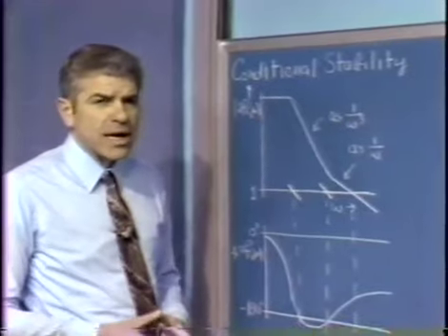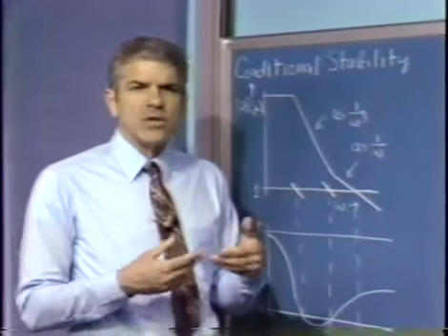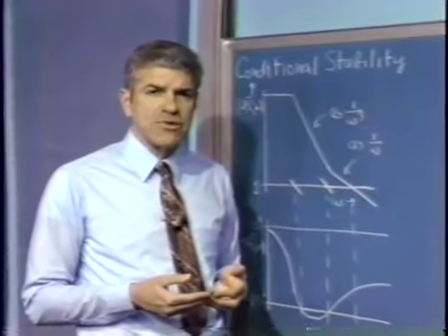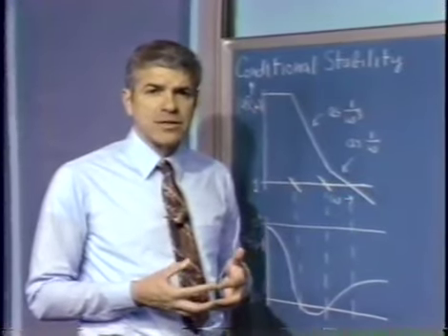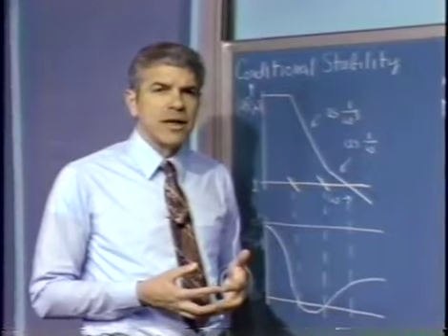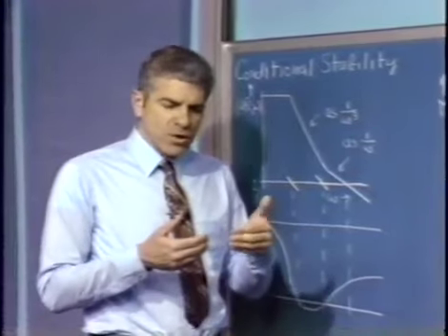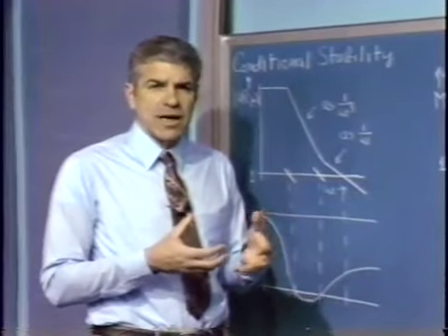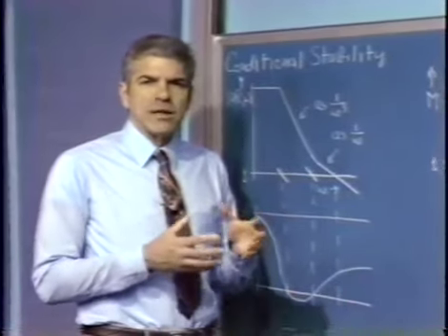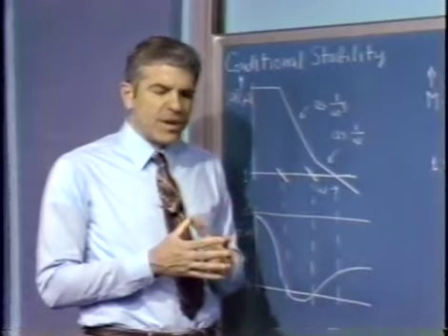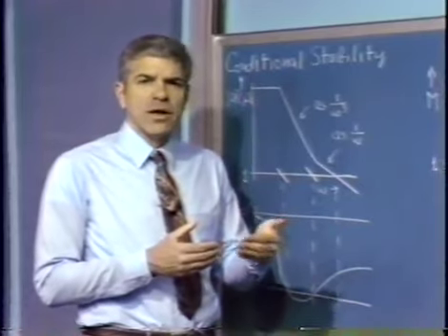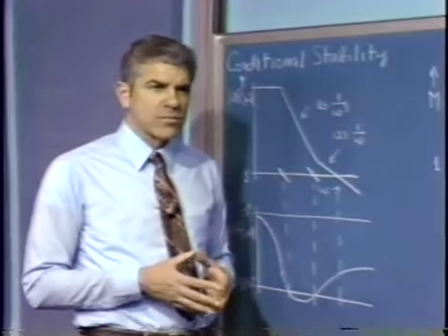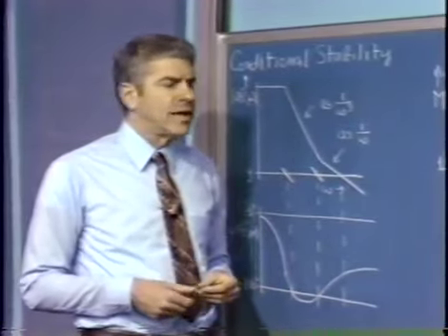We found out when we looked at operational amplifiers that there was a whole collection of higher frequency poles. There was a phase shift associated with the lateral PNP transistors that are used in those operational amplifiers. And that collection of poles, the phase shift associated with time delay basically, really as a realistic possibility forced us to cross over at some frequency that was bounded by possibly a megahertz for the usually encountered operational amplifiers.